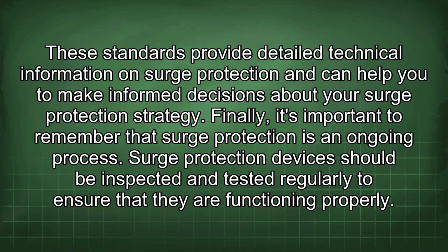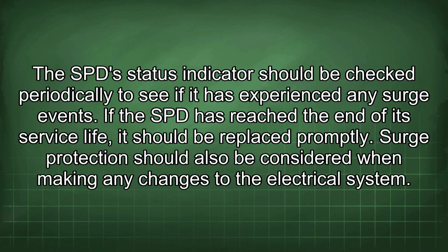These standards provide detailed technical information on surge protection and can help you to make informed decisions about your surge protection strategy. Finally, it's important to remember that surge protection is an ongoing process. Surge protection devices should be inspected and tested regularly to ensure that they are functioning properly. The SPD status indicator should be checked periodically to see if it has experienced any surge events. If the SPD has reached the end of its service life, it should be replaced promptly.